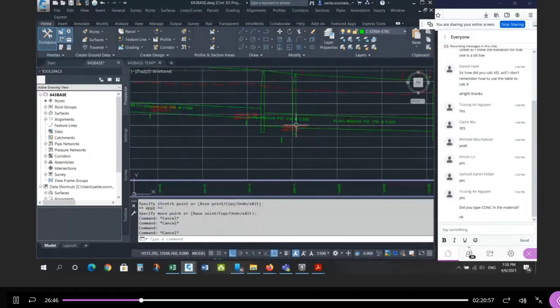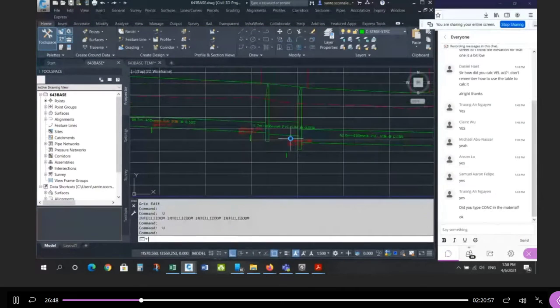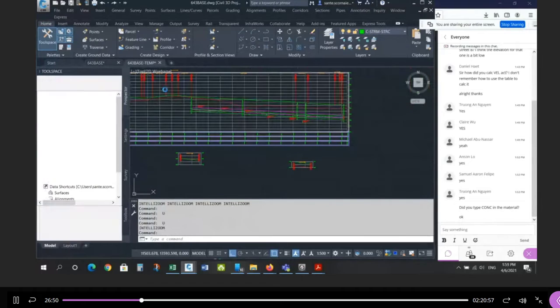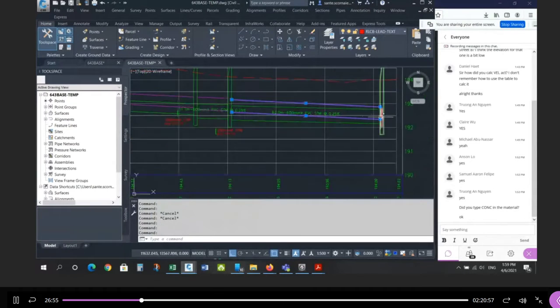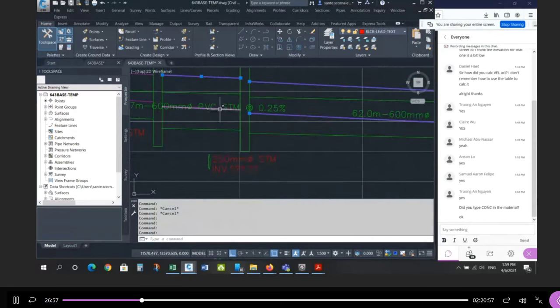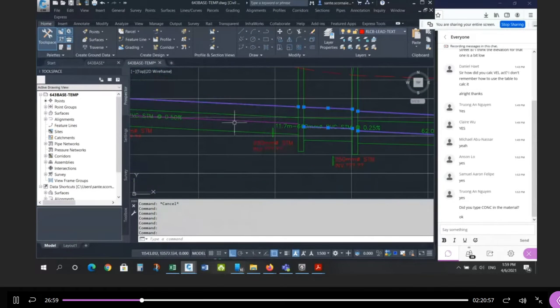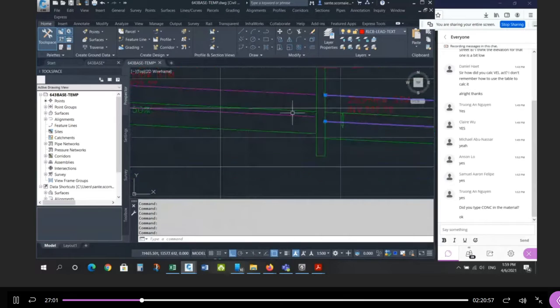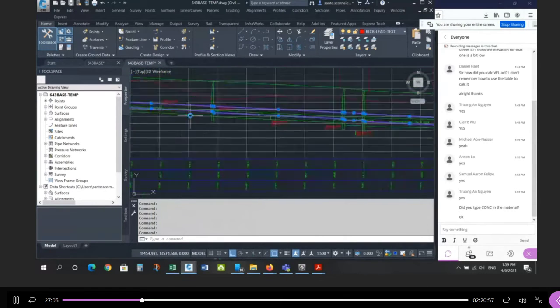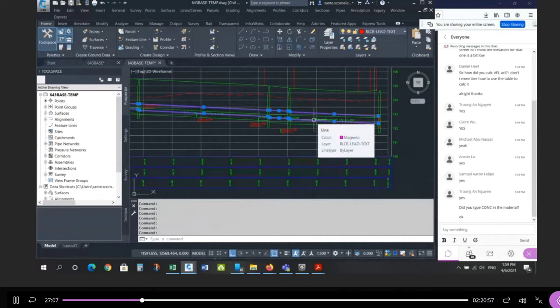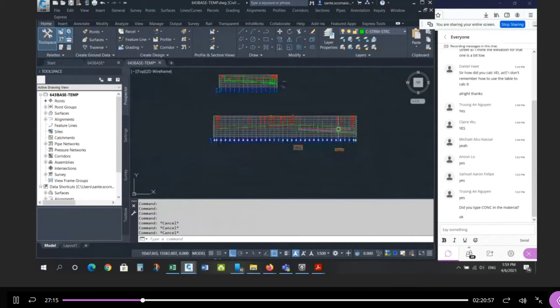And then this one ended up coming down, and the last pipe came down as well, okay? So without redoing everything here, I'll just show you what the result was, right? This purple line, this magenta line, those are the original pipes before I made this revision, the 0.5% pipes with the other sizes. So here's where the sewer used to be, and I've pushed it down by about 1 foot. Now, it doesn't sound like much, 1 foot, but it's significant because I'm trying to get down as low as possible, okay? So that's the revision you make, okay?